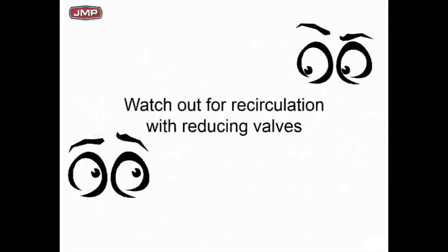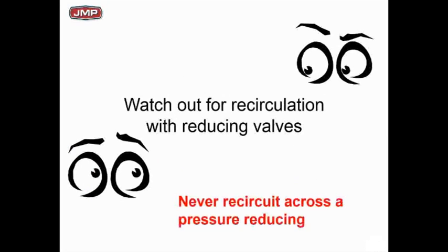So simple little comment: little check valves coming out of domestic hot water recirc lines in every case, however they tie in. I mentioned to you to watch out for hot water recirc pumps across pressure reducing valves. I've said to you, never do it. I can't scream in this, but if you were in one of my seminars, I'd be pounding the table right now because I see so many people make this mistake. On a high-rise building, do not take a domestic hot water recirc pump and try to recirculate it across pressure zones, across pressure reducing valves. It will be a problem.